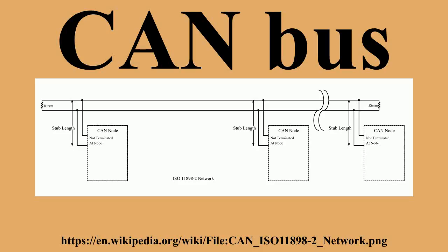This resynchronization process is done continuously at every recessive to dominant transition to ensure the transmitter and receiver stay in sync. Continuously resynchronizing reduces errors induced by noise, and allows a receiving node that was synchronized to a node which lost arbitration to resynchronize to the node which won arbitration.